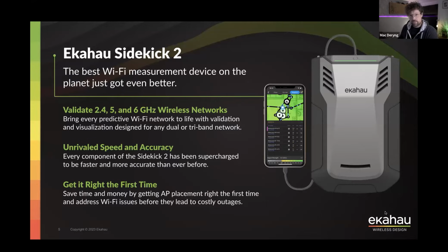We don't want to be using dongle spectrum analyzers because we need to have 3 of those now for 2.4, 5, and 6 gigahertz. That's another USB hub connecting to our laptop. If you have the 6 dongles, our battery life goes down extremely quickly. And we don't want that, right? We want to enjoy doing a survey as long as we want to, as long as we need to, having everything inside a single device.